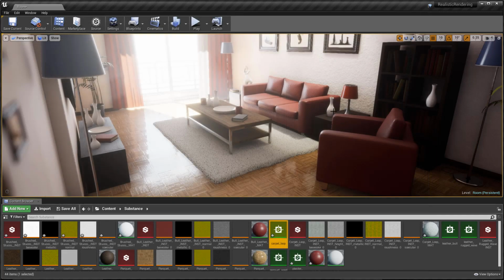So that's going to close out this basic tutorial on Substance in UE4. In this video, we talked about installing the Substance plugin, importing Substance files, using Substance Source to browse for substances and download them directly here into our content browser. We also took a look at a few examples on how we were able to open up a material that was generated by the Substance plugin and add additional nodes to further extend the capabilities of that shader. And lastly, we looked at changing the Substance Generation mode as part of the Substance project settings on a global basis as well as on a per substance material.